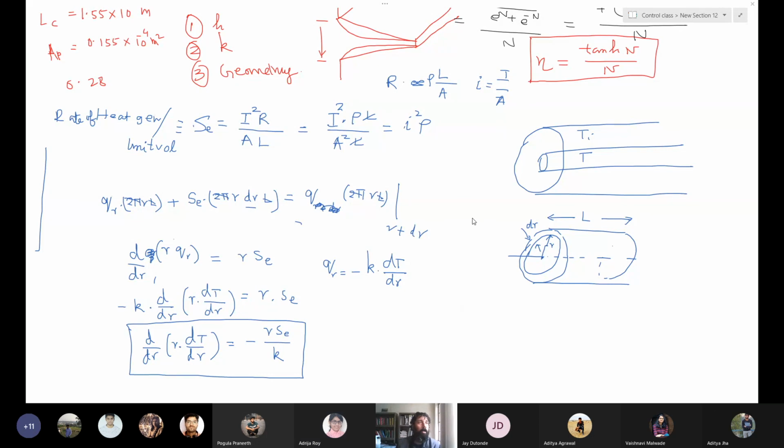I think I understand that you are learning boundary layer theory in convection, right? Yes, sir. What is the thickness of boundary layer? Sir, I don't remember the formula, but it's where the temperature gradient is 0.99 of the maximum. No, that's fine. That's the definition of the outer edge of the boundary layer. The typical thickness of a boundary layer is about a millimeter or two. So if you keep two fins 4 millimeter, 5 millimeter, half a centimeter away, then the boundary layer will not even be thicker than half of those. So the question is how close is close? If two boundary layers do not touch each other, that is far enough.